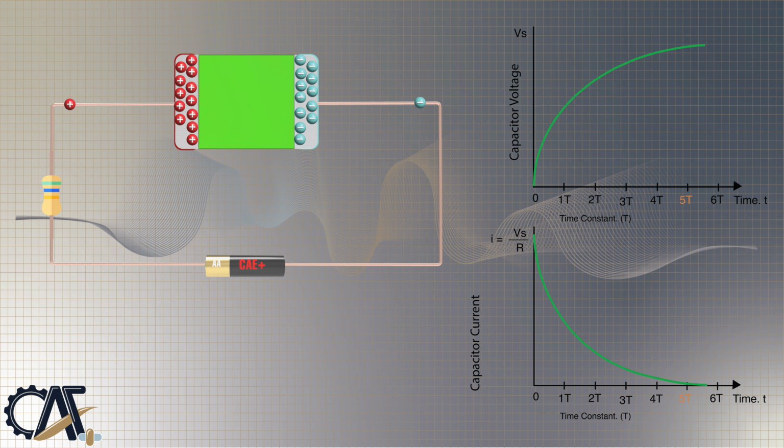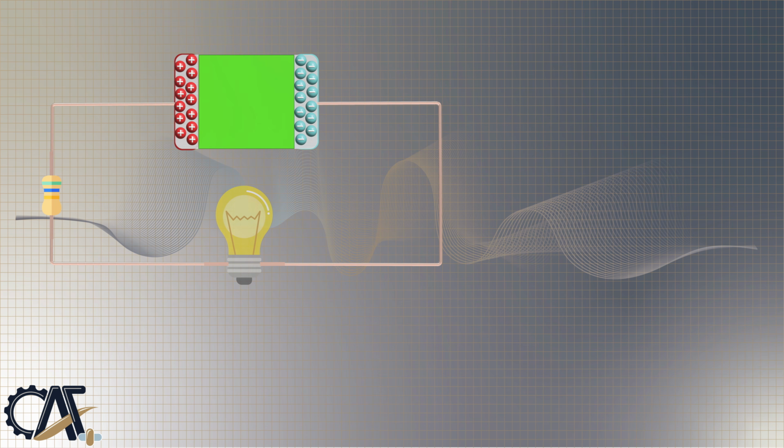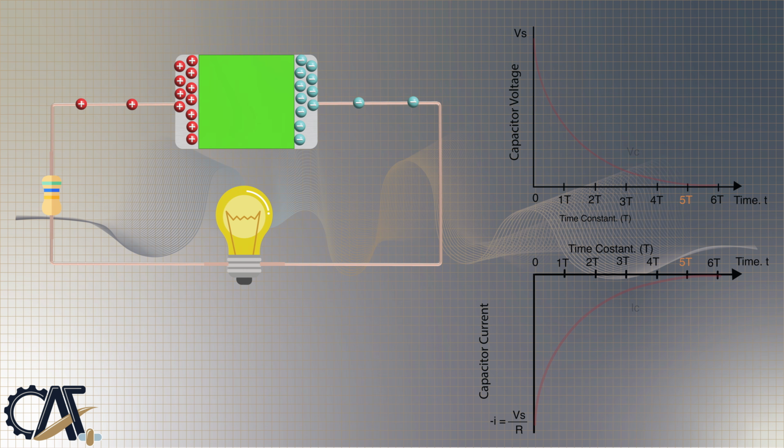The rise in the RC charging curve is much steeper at the beginning, because the charging rate is fastest, due to the higher voltage difference between the battery and the capacitor at the start of charge, but soon tapers off exponentially, as the capacitor takes on additional charge at a slower rate. Although they work in completely different ways, capacitors and batteries both store electrical energy.